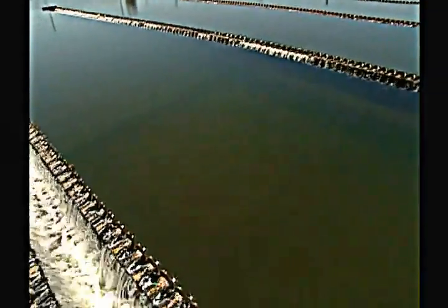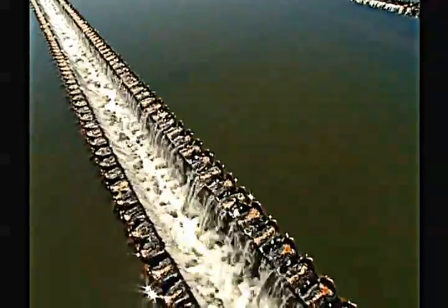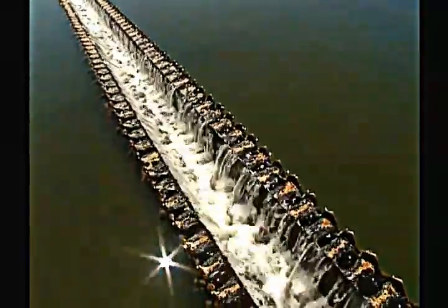There are all different kinds of sedimentation processes, but generally they all work by gravity. Take advantage of the fact that gravity's free and always works. So generally the water is traveling horizontally and the floc particles are settling vertically. And hopefully the particles settle to the bottom of the basin before the water gets out of the basin.